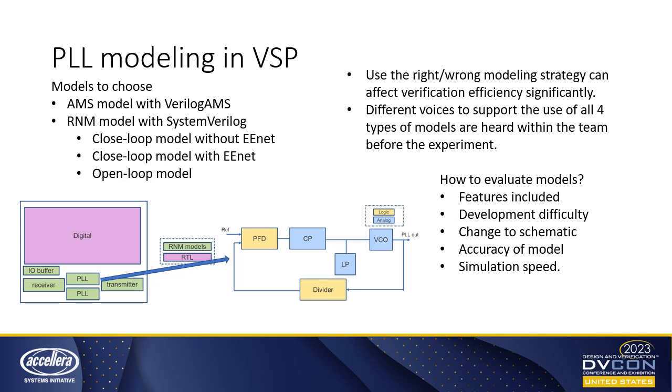We were looking to improve our verification coverage in the video signal processing product line, and we had multiple existing PLL models to choose from. Unfortunately, these models were designed with different purpose and scope and mainly meant as prototyping models or digital simulation crutches. The AMS models are generally too slow for full chip verification, and the open loop discrete model didn't provide the necessary coverage for verification targets.